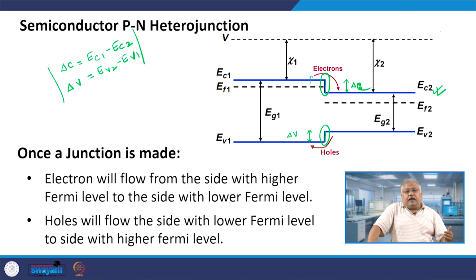So, when you add those two together, in order to make the Fermi level equitable, I can say that electrons will flow from a region of higher concentration to a region of lower concentration, and they will try to make the Fermi levels balance out with respect to each other. Now, please keep in mind that while doing so, I have not changed the value of the electron affinity or the band gap. They are always constant depending upon the type of material which you have chosen.